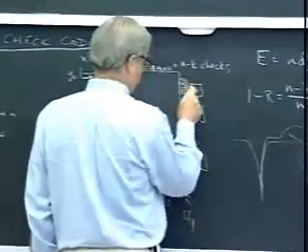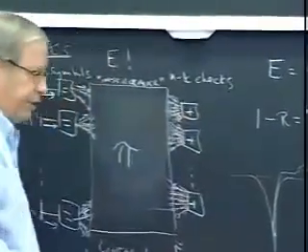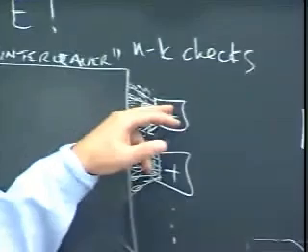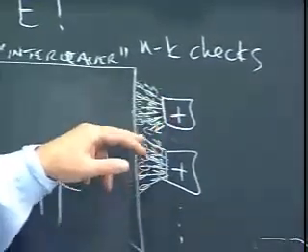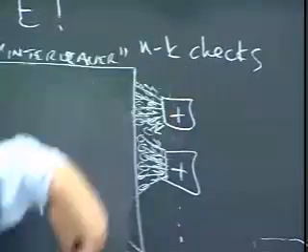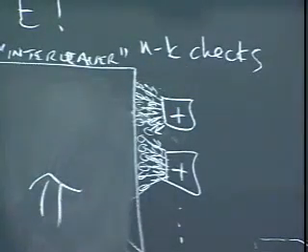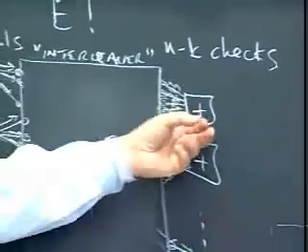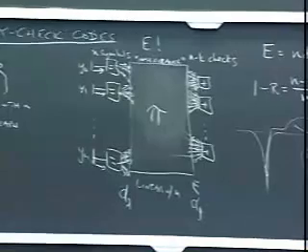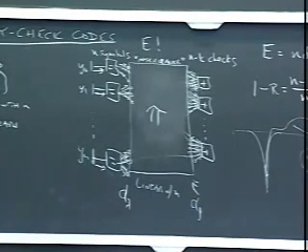Each one of these is based on the D row minus 1 other inputs. All right, so it ignores the message that's coming in on that particular edge. It uses all the other messages to give an extrinsic message going out, which you could combine back here or here, the same thing, to give you your best overall APP right now from your right-going and your left-going messages.